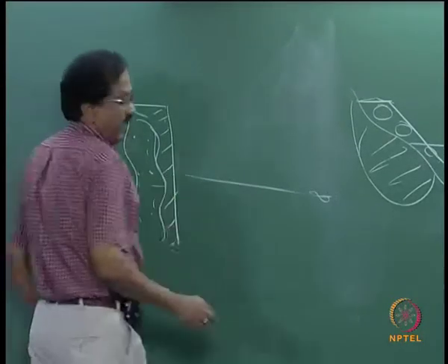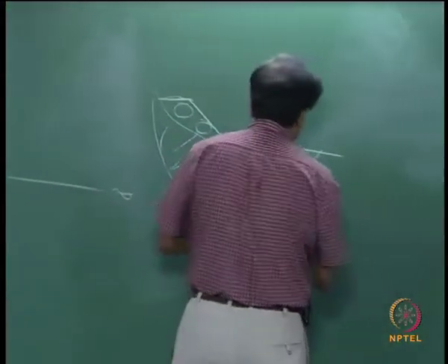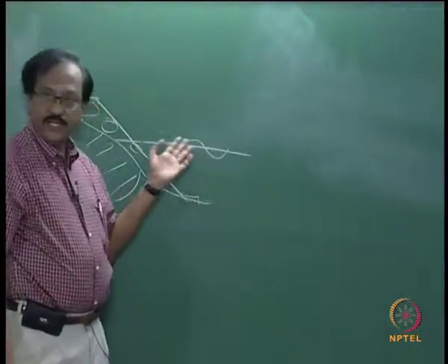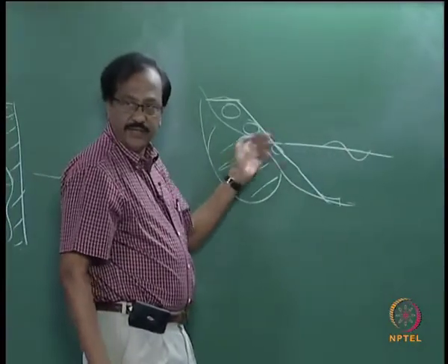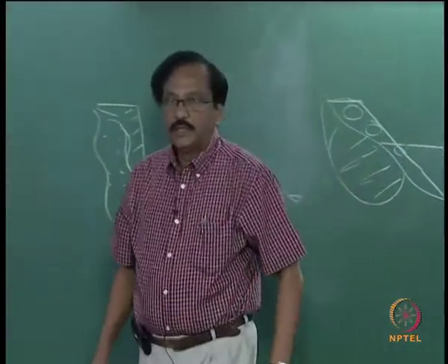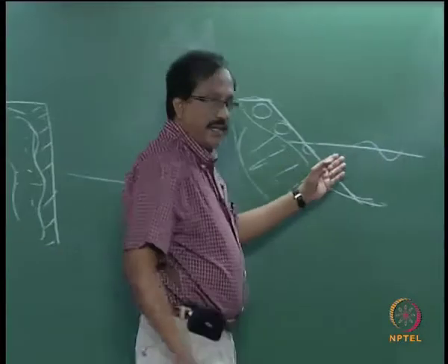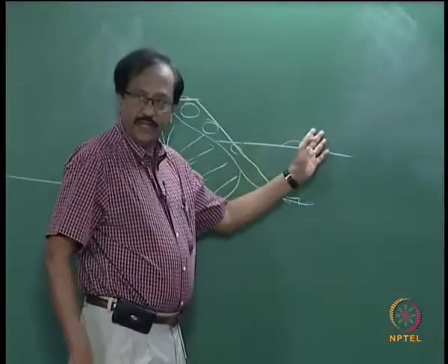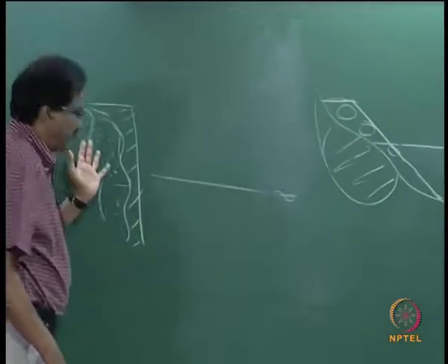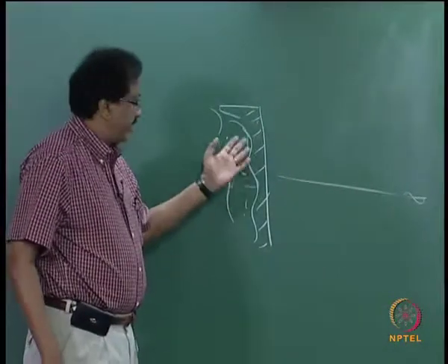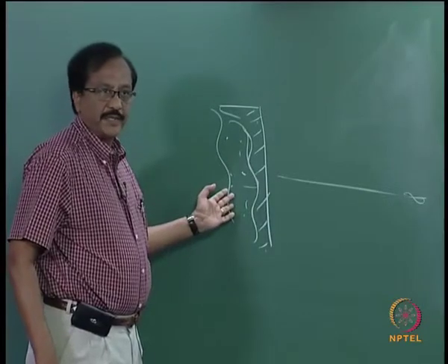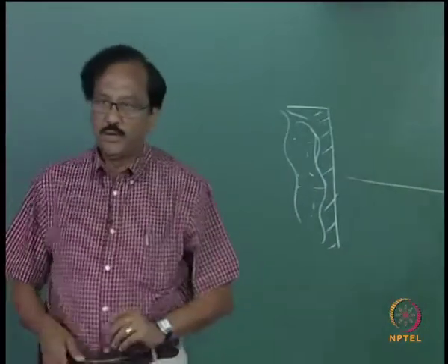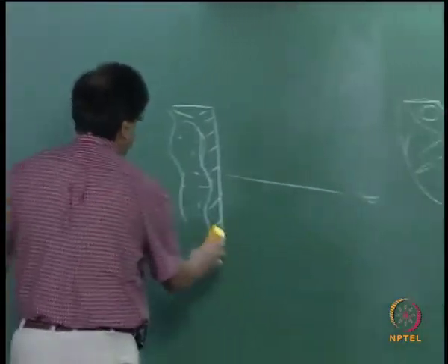Okay. For example, if there is not much wave action and only very occasionally you have the waves coming and hitting the structure, then it is termed as bulkhead. So, here the major force which is coming on a sea wall is that due to waves, and in the bulkhead the major force that is coming on the bulkhead is the earth pressure. So, that is why they have two different names, sea wall and bulkheads.